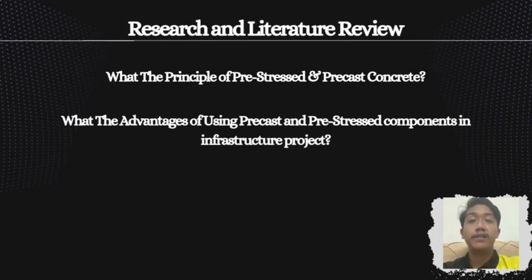What are the advantages of using precast and pre-stressed components in infrastructure projects? Number one, reduction of cracking due to permanent pre-compression. Number two, better corrosion resistance. Number three, reduction of building weight, like foundation savings.